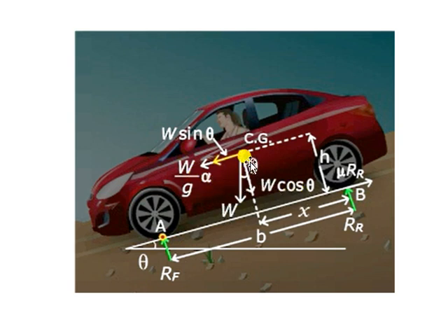Due to which you can see a vertically downward force for the weight of the vehicle. Similarly, vertically upward forces on the tires, on the wheels, are the reaction forces. And since the vehicle is moving in this direction, the friction forces are also acting on this vehicle. Let's say mu into Rf is the friction force for the front wheels, and similarly mu into Rr is the friction force on the rear wheels. And since the vehicle is placed on an inclined path, this W can be broken into two components.